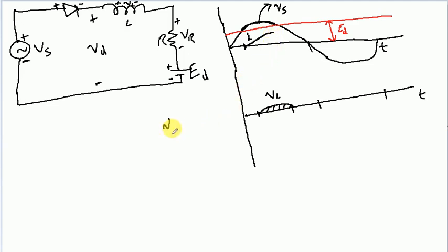As we know from this relationship, once this rate of change equals 0, the voltage across the inductor will also become 0. That is the point at which the inductor voltage becomes 0. After this point, if we did not have this inductance, it would have caused this diode to immediately become reverse biased and the current would have become 0. But since we have this energized inductor, it will not allow the current to become immediately 0. The current will start approaching 0, with a falling slope from this point onwards up to a specific point. That depends on the actual value of the inductance.